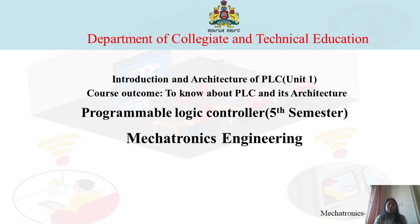First, all the input signals are monitored, and the input signals we get are stored in the RAM. In the RAM it is divided into two sections: the input image file and the output image file. Then your CPU fetches the input variables from the input image file and processes them according to the program you have written using the programming device, and then the output image file is filled by the CPU. Then according to that, your outputs will act. So we have seen up to the IO modules.